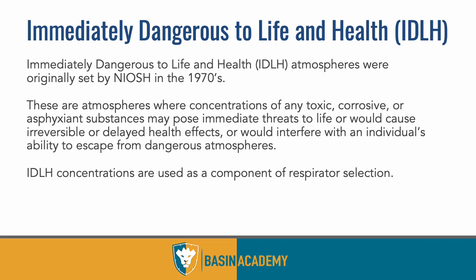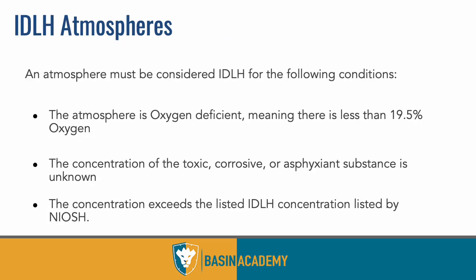At that level, a respirator is required, like a full face piece respirator with supplied air, so that you're not breathing it in, so that it's not impacting your lungs, etc. And that's for any toxin. For H₂S, that's 100 parts, and for SO2, it's 100 parts. But what we're seeing is that SO2 is known industry-wide to affect you at half the levels of H₂S, but the record books and the OSHA rules kind of put it in the same category, so keep that in mind.